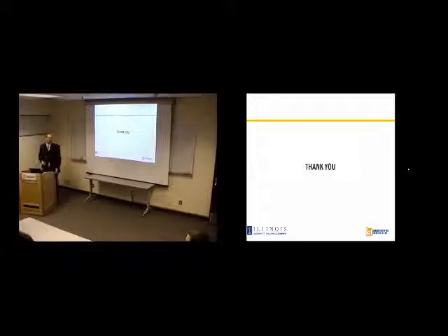Right, and if you think back to the analysis phase, where I was showing a very general overview of what this IPAS, image processing and analysis system, was capable of, I focused in this presentation mainly on aggregate proximity. One of the other options was orientation, and the reason we set it up so that you could define it as vertical or horizontal on the screen, or radial, is because it's going to be heavily dependent on your compaction method. Gyratory may influence it in a radial pattern. When you're taking a core from the field, you need to be able to identify longitudinal versus transverse direction, in which case you would use strictly vertical and horizontal orientation on the screen.